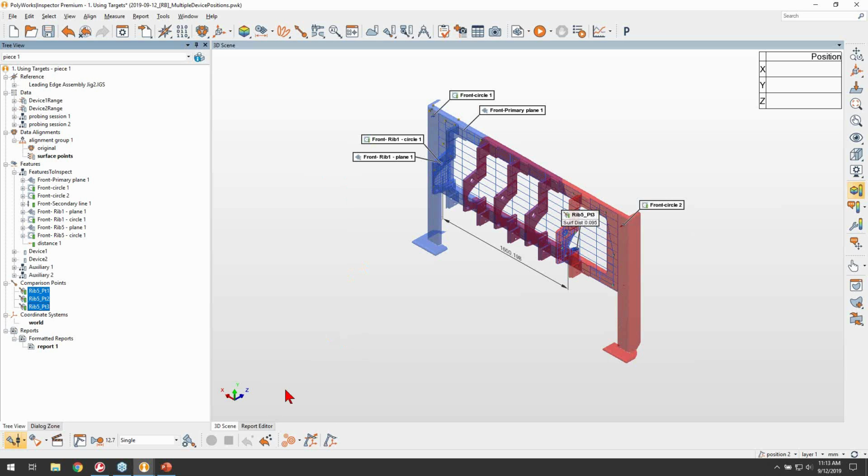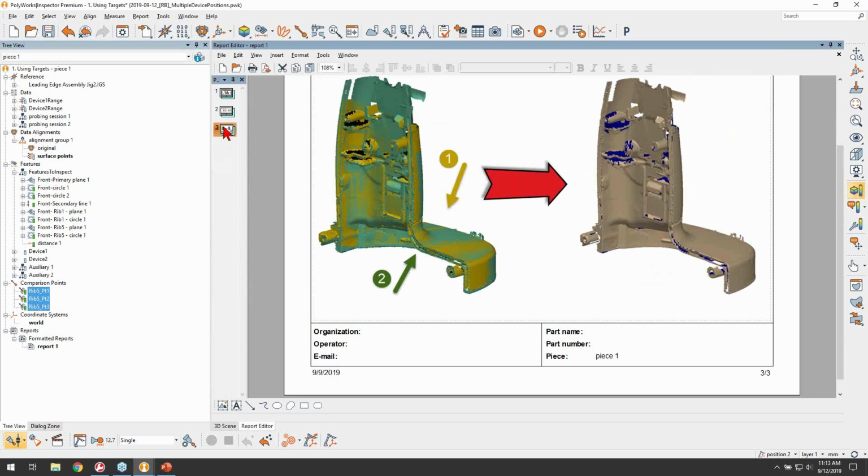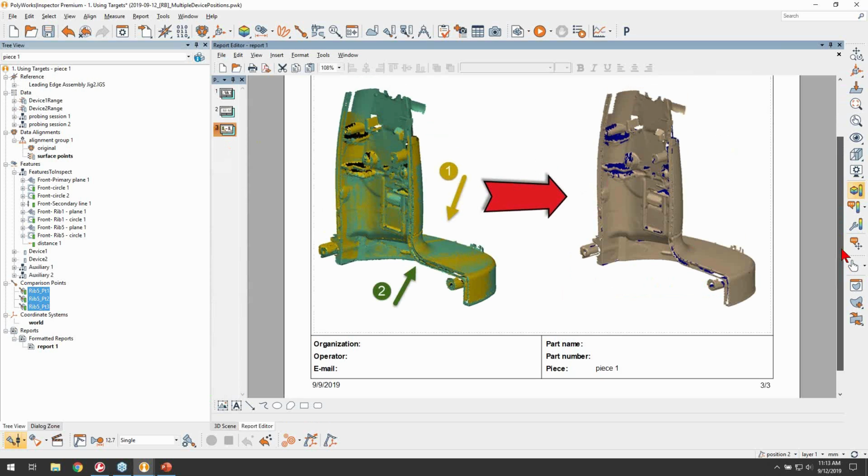This will become even more obvious in our next scenario, in which our goal is to get front and back coverage of a part while scanning. This is a very common task in reverse engineering applications, but also in inspection, especially for cylindrical parts or when analyzing part thickness or 2D section profiles.